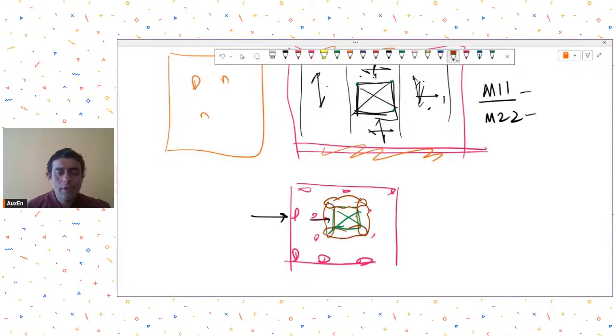So in such cases you have to carefully look at these regions around the opening and study their load path, especially if the lateral load is in this direction as I'm showing you right now. Let's call it EQX. Then these elements are important and we usually call these elements the collector elements.